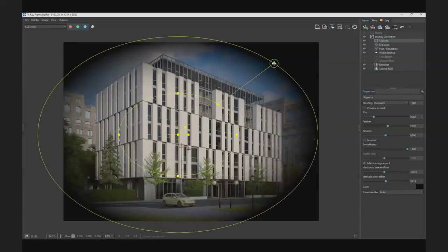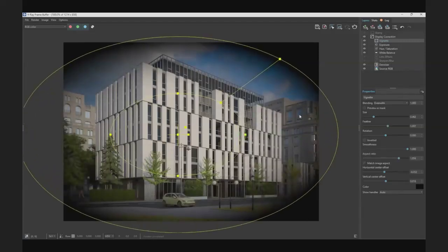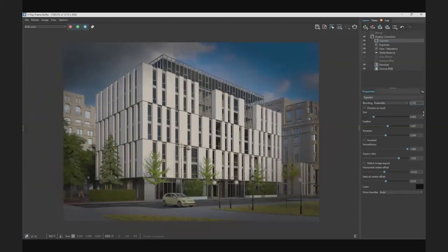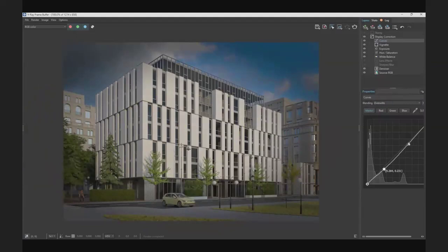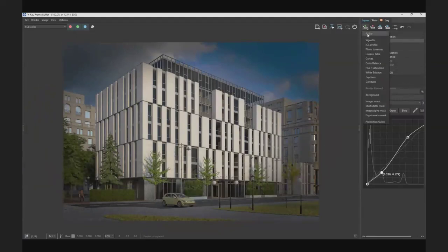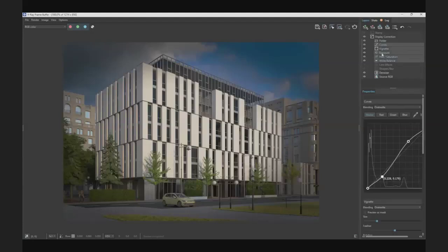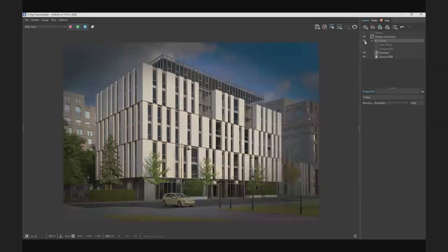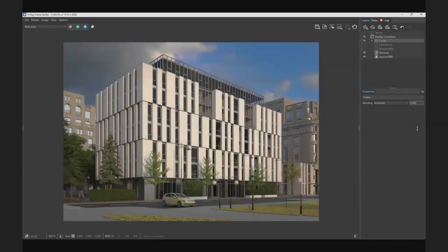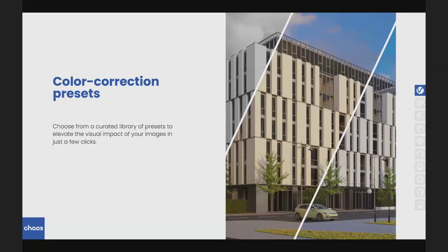And we wanted to have that in the images in that project. So with most of the images, we've added that directly right here instead of going into Photoshop or another image editor. We have applied that render elements directly here. Also, we are using a lot of different color corrections here. Our goal was to create all of these things directly in the frame buffer. As I mentioned, instead of going out and making these changes elsewhere in some image editors like GIMP or Photoshop.